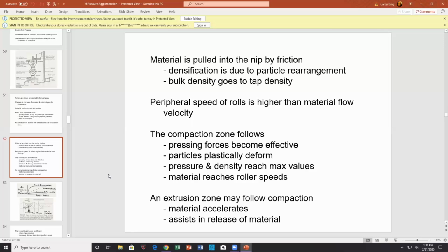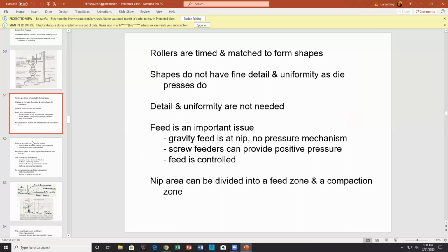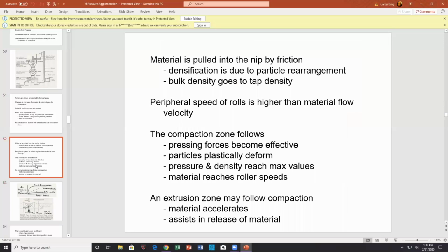Anyway, you have a lot of interesting things here. First off, you have feed here. You have motion, you have material, so you have a potential for static buildup. You haven't had any sparks come off that feed pipe to the rollers, have you? So I can envision roll crushing where there's static charge buildup. Anyway, I always want to watch out for static charge myself.